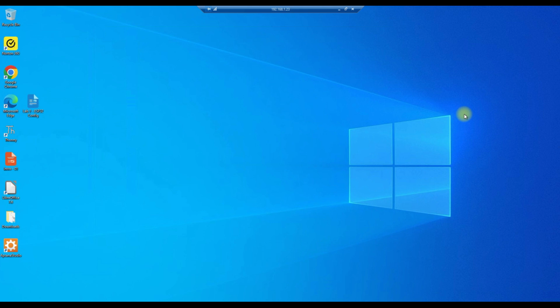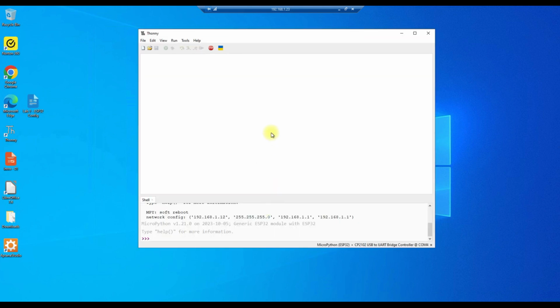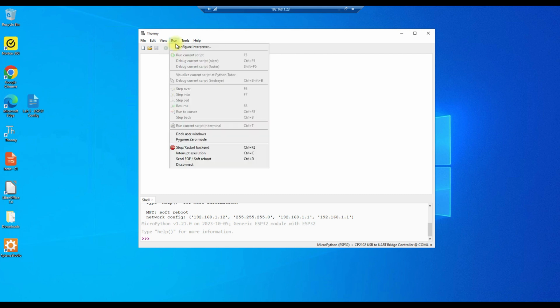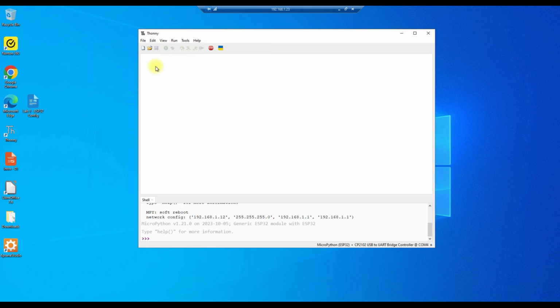Now that we've created our listener, our next step is to configure our ESP32 microcontroller. So in this step, we are going to open Thonny, and if not already done, connect the microcontroller to our workstation. Once it's connected, we'll hit run, stop, restart backend to establish our connection to the microcontroller. Let's open up our folder here, which gives us the option to access the computer or MicroPython. In this case, we want to access the MicroPython device.